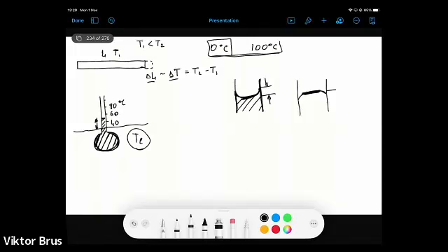So that's why there is special information, like in passports for thermometers, which provide appropriate coefficients and equations to take into account this error of the external pillar of the mercury, which is located outside the environment in which we measure temperature.